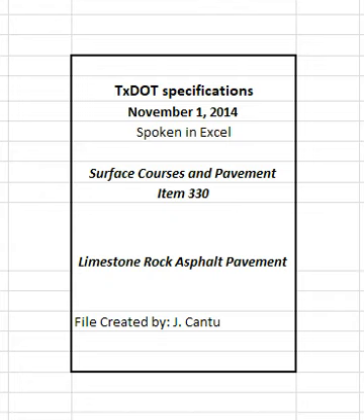4.1.1 Project Personnel. For project personnel, include a list of individuals responsible for QC with authority to take corrective action, and current contact information for each individual listed. 4.1.2 Loading and Transporting. For loading and transporting, include type and application method for release agents, and truck and rail car loading procedures to avoid segregation.